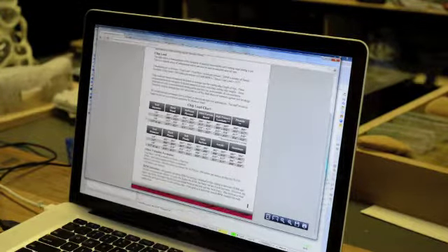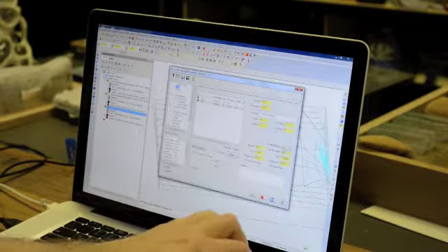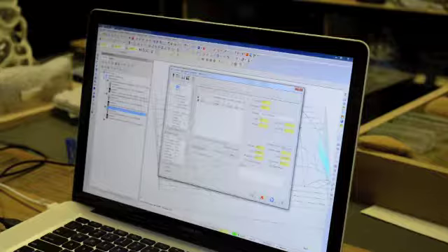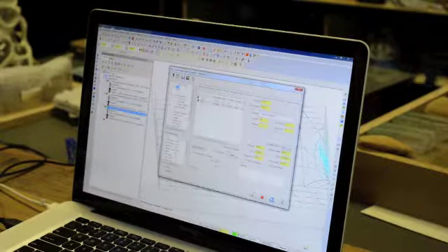Alright, so do you want to stop and we'll just do the calculation? It's going. Alright, so we calculated our chip load chart value and came up with the spindle speed of 28,000. So you can see there's a big difference.